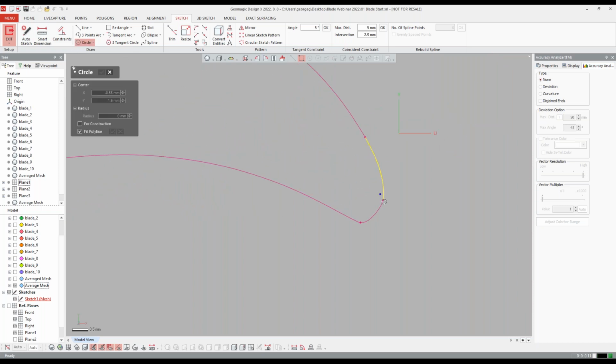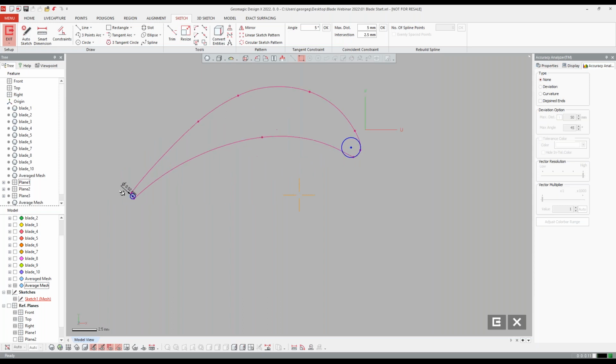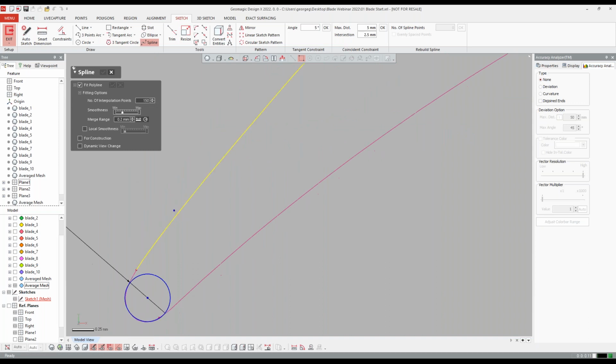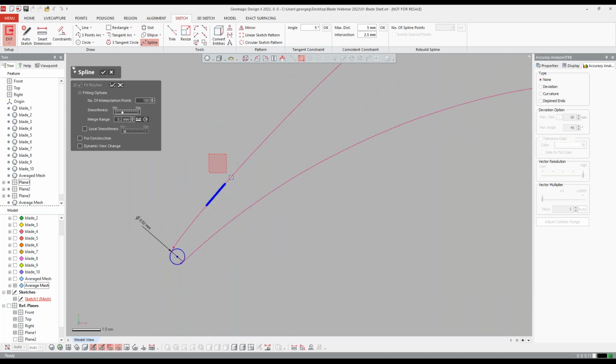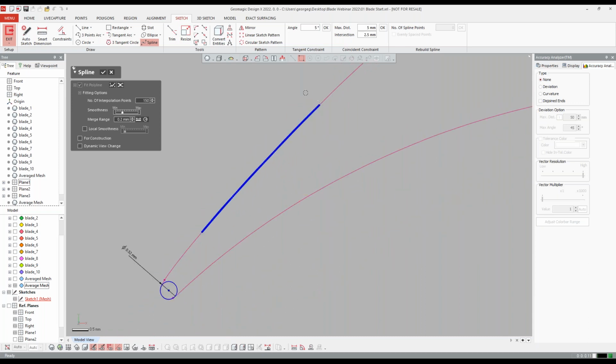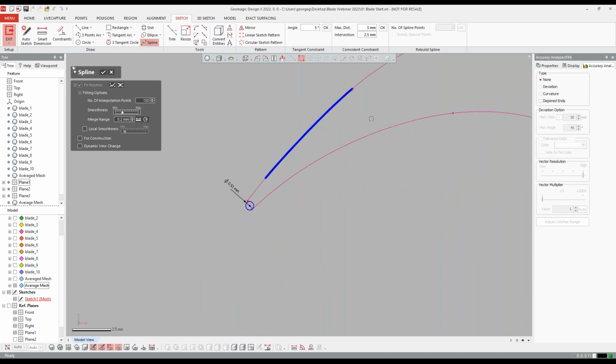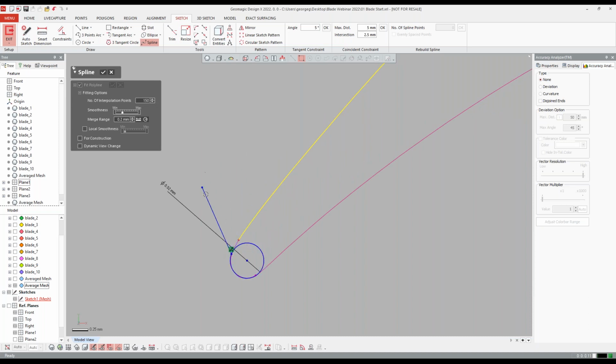And the same thing goes over here. If I wanted to window in and fit a circle to that information and accept it. Now for this arc side, there's a bunch of different ways. I can use that same selection and fit splines to that information just by windowing in if I want to. That's one way. Or I can manually draw the spline how I want it to be. So I can click on that circle and snap to it this way as well.